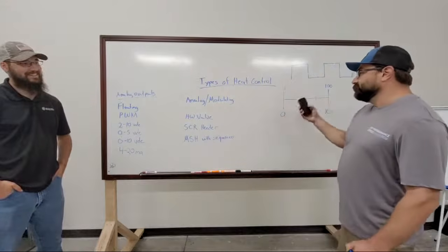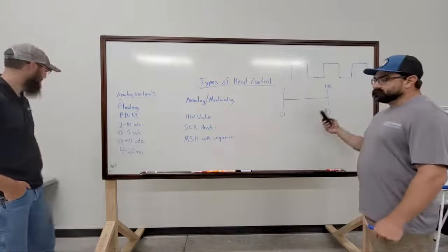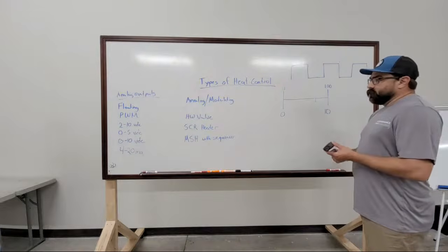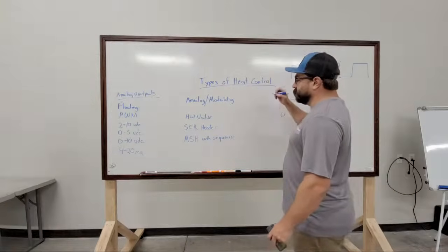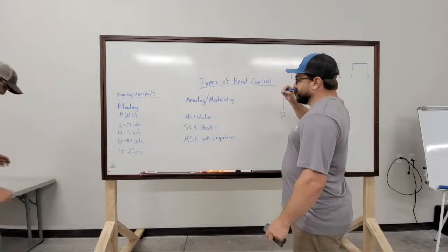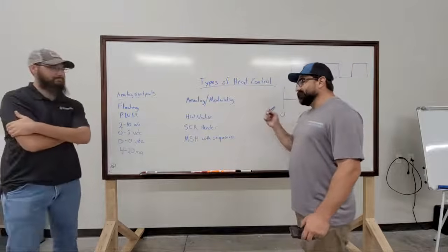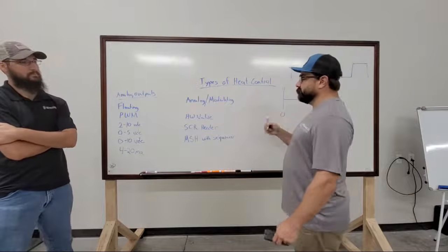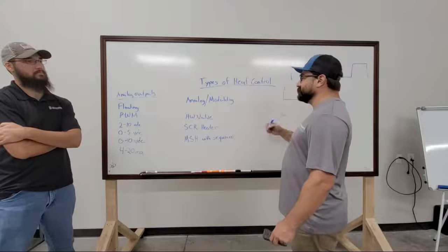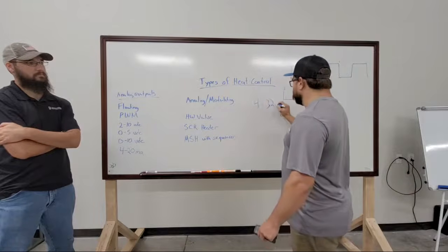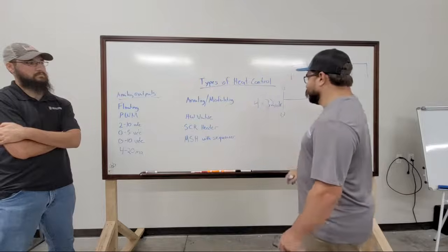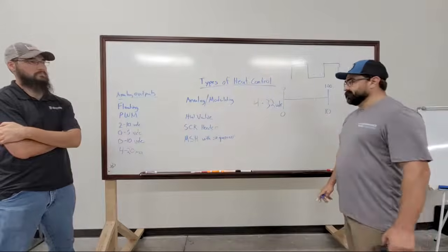Like I was saying, it can be volts AC, it can be volts DC. Like I wired up a heater the other day that was pulse width. It was actually an SCR heater that required a pulse width modulating DC input. So basically anything from 4 to 32 VDC would bring that SCR on and open the gate.